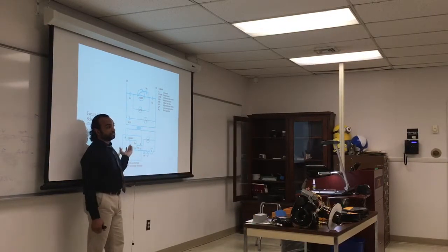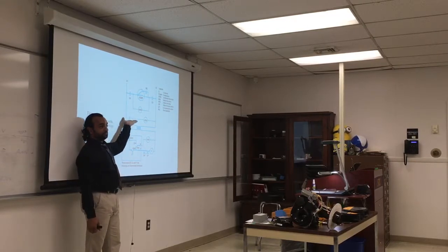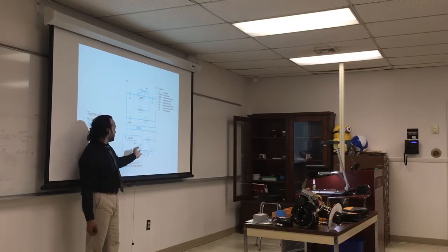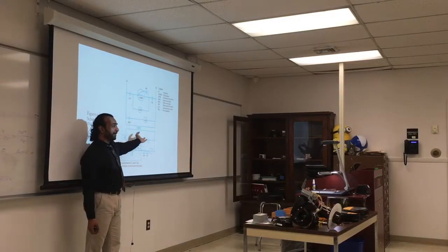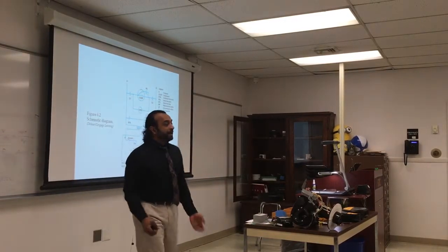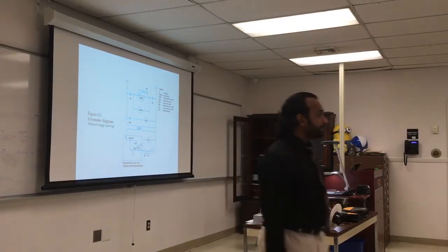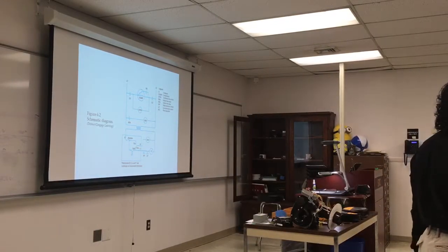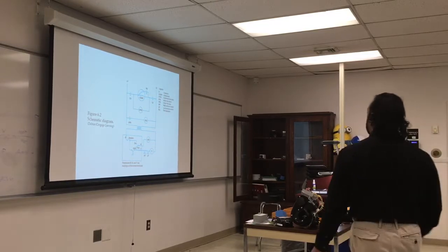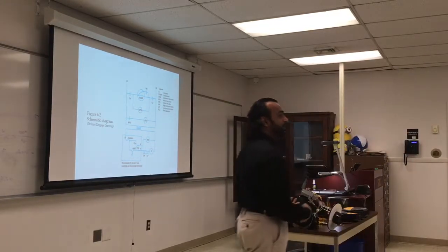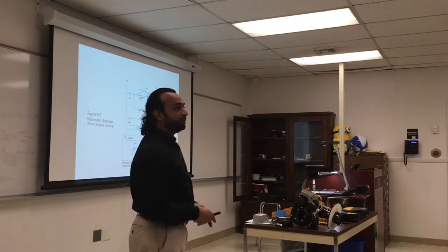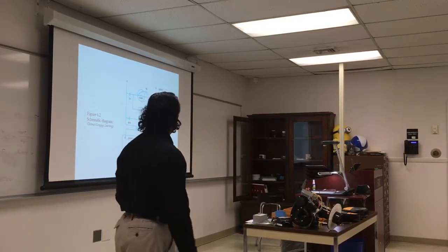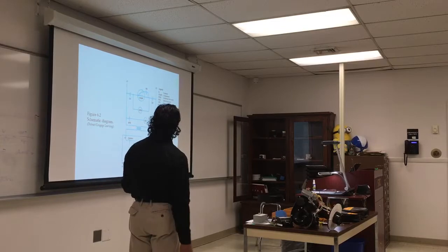What do you think? Follow from the top to bottom. Look at the legend. You can tell it's an AC by knowing the components: thermostat, compressor, fan. And again, everything the first time looks a little bit overwhelming. Once you work on it 2 or 3 times, it seems very familiar. Like everything else in life. In the beginning, it's a little bit ambiguous, dark, but don't get overwhelmed. Look at it and try to decipher those symbols.